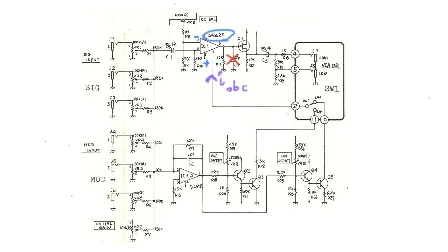So the last thing I want to do here is talk about these capacitors. There's some that I've basically ignored entirely, and that's this 10 microfarad 25 volt cap at the input and this 10 microfarad 25 volt cap at the output. These are just DC blocking capacitors that block any DC offsets in the signal. And you can tell that because they're very high capacitances for audio.